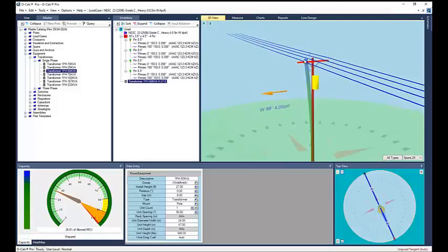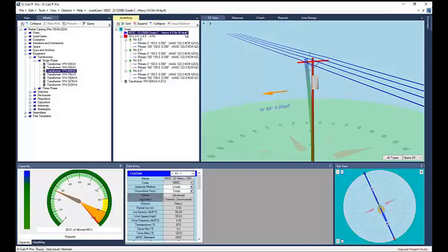We're seeing a deflection path bar here indicating the movement that would take place with the pole given the current conditions that we see here with this load case, 4 pounds per square foot of wind and a 1/2 inch of radial ice on our conductors. So we're talking here about a wind speed of almost 40 miles per hour and radial ice on those conductors.